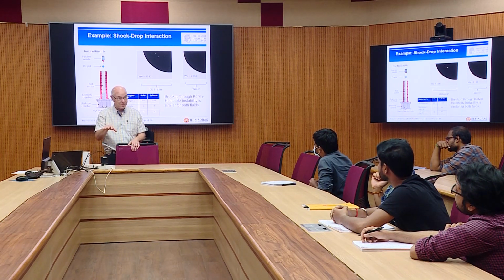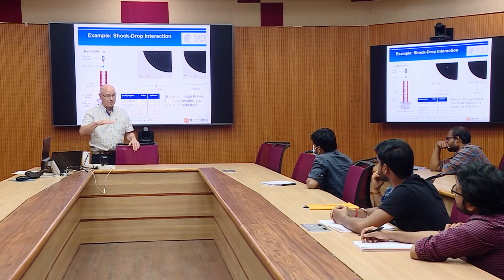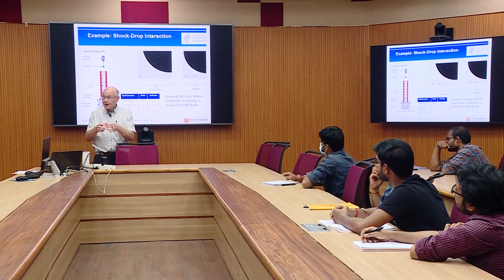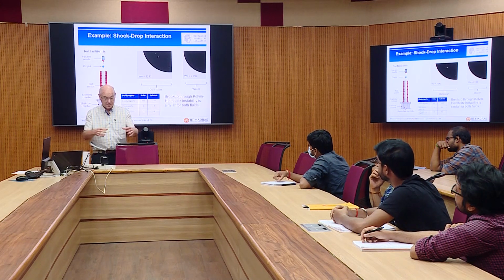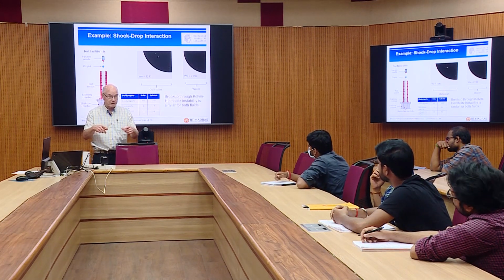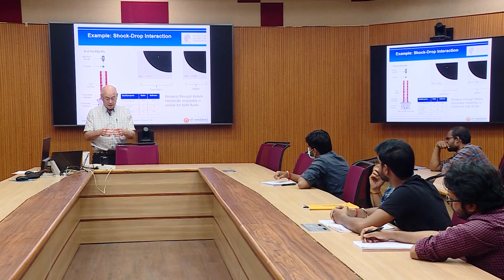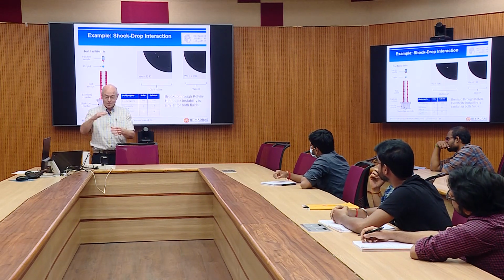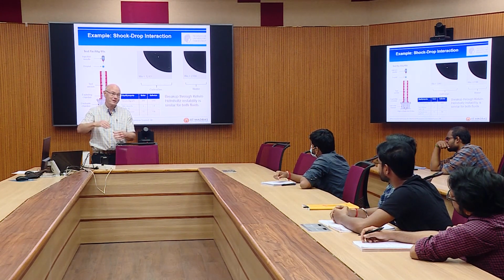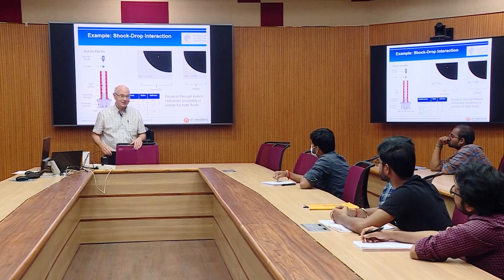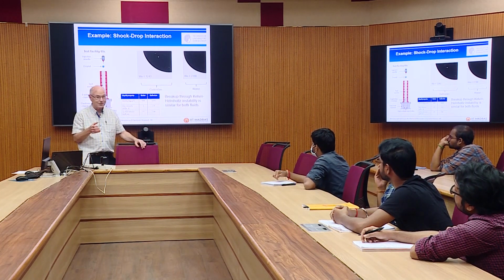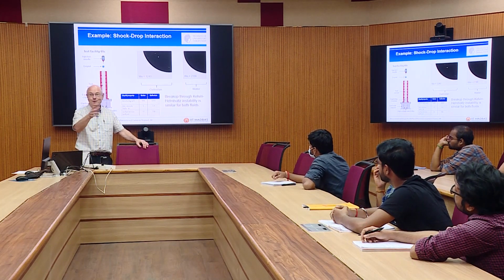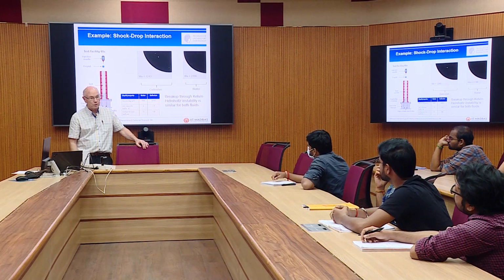And the inkjet printer is very similar. You have to have some disturbance, and instead of vibrating the hole, because typically these inkjet printer heads have 300 or 400 holes in them, instead of vibrating the whole thing, you have a piezoelectric transducer on the volume above, and you vibrate the pressure. You make a pressure oscillation, and that's the disturbance. So now we are talking about how you make the disturbance. That's how the inkjet printer basically works.